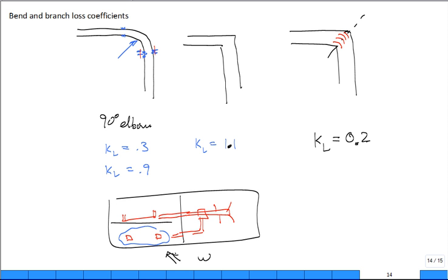And when I went up there and I looked at it, this had been a very hard mitered 90 with no turning vanes. Nowhere else did it have any. It was just straight runs, no hard turns. And when you took a look at the equivalent diameter for that, it was like a 12-inch equivalent diameter, 1 foot equivalent diameter. All right. And then you have it mitered, and so then you have that loss coefficient. If you go back to the length equivalent concept, just to help you get in perspective, okay, what is the effect of just this one mitered 90 right up here with no turning vanes?